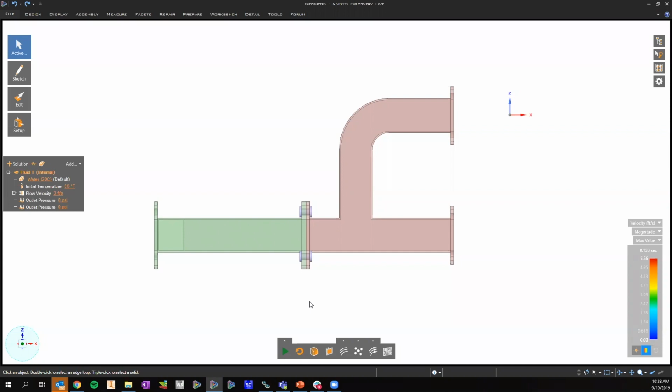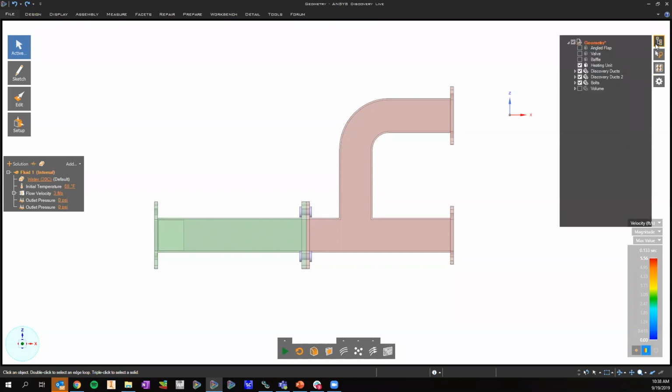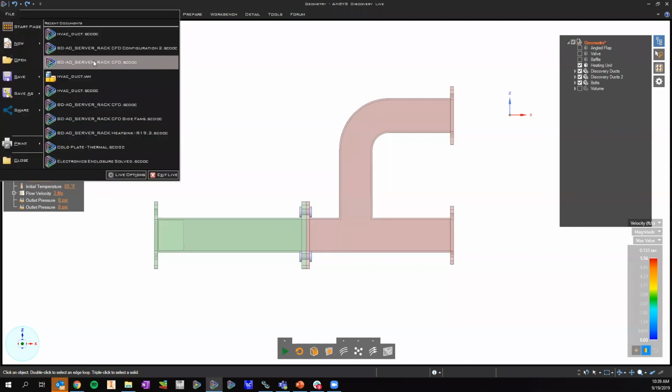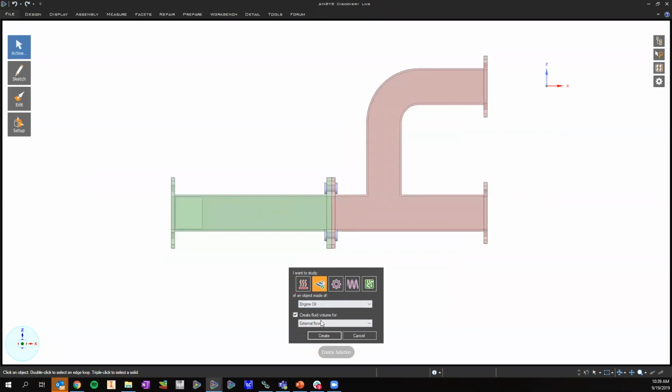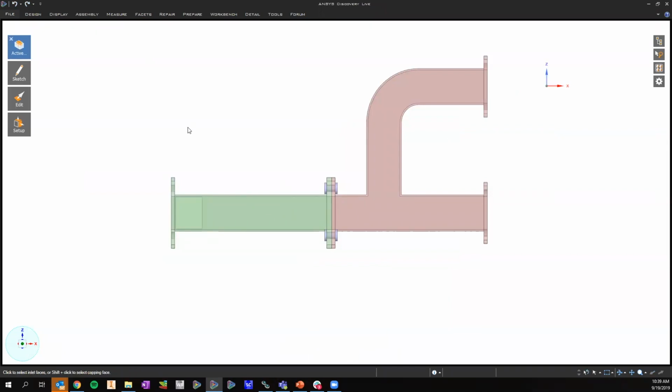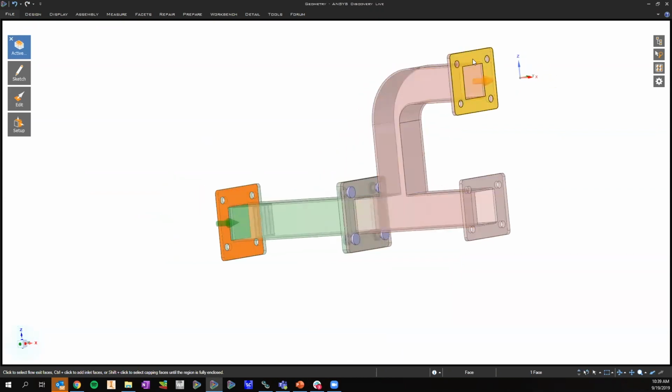Yeah, my bad. The question was, does this environment allow multi-fluid flow? So absolutely, I can apply multiple boundary conditions. The only thing we don't do is mix. We don't do any mixing and any non-linear type of setups here. So if you want to have a liquid at one temperature and another liquid at another temperature, and you want to see what the result is at the outlet, or air at multiple temperatures and multiple locations, those can all be done, but I wouldn't be able to mix different types of fluids together. So it wouldn't be this application that would be the one to do that.